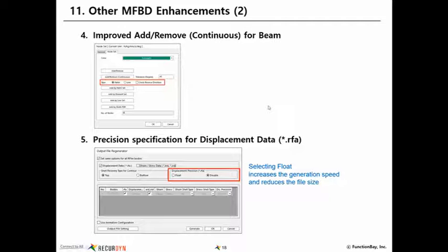That one is for when you have a mesh with shell elements. The shell elements have a 2D topology, but there also is a thickness. If the shell element is being bent, then the stress on one side will be different than the stress on the other side because of the thickness. As far as the display is concerned, you have to pick one because it's a 2D topology for display. So you just pick top or bottom so that you can see what the stresses are on the two sides of the shell.